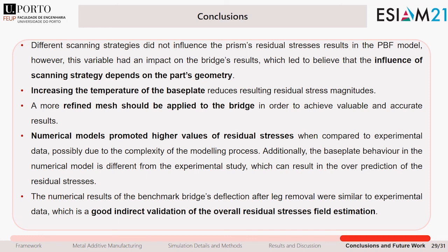Numerical models promoted higher values of residual stresses when compared to the experimental data, possibly due to the complexity of the modeling process. Additionally, the base plate behavior in the numerical model is different from the experimental study, which can result in the over-prediction of the residual stresses. The numerical results of the benchmark bridge's deflection after leg removal were similar to the experimental data, which is a good indirect validation of the overall residual stresses field estimation.